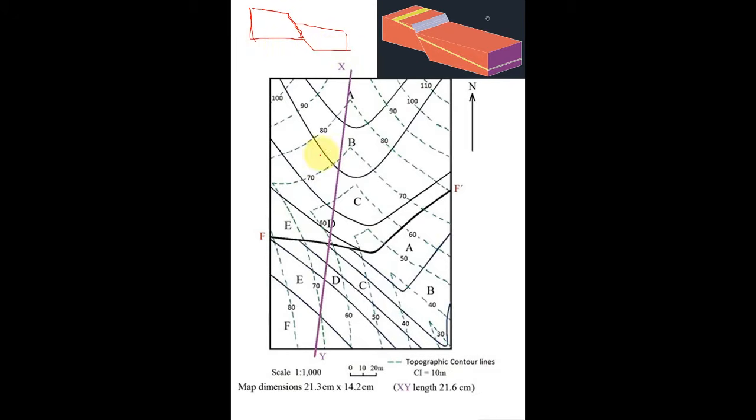The interesting part to note is that the inclination of the rock on this part is the same as the inclination of the rock on this part, right? So this inclination is not going to change because of faulting. That is what you need to understand. If that inclination is not changing, it directly says that the strike lines are going to be at the same distance in both the parts. So here in this map, if FF dash is the fault line, this entire thing is one part, this is the other part, right?